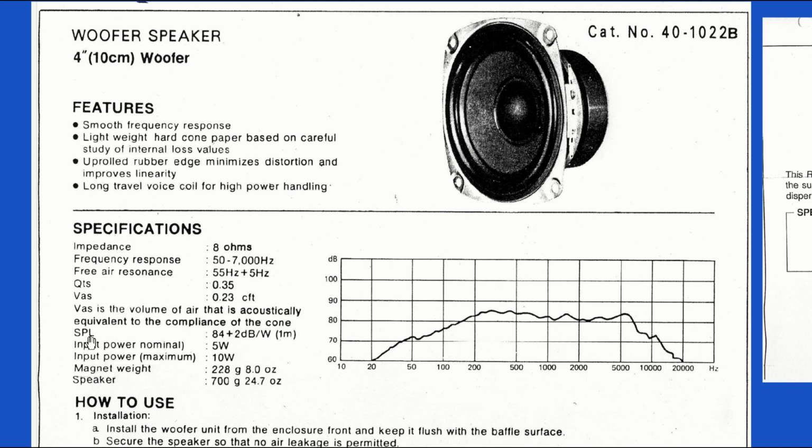At what frequency? Well, again, let's go over and look at the graph. So it looks like by the time we get to 200 hertz, we're pretty close to that 84. This is 80, this is 90, so 84 is close to the middle, so we're talking about basically a line right here. So 2 or 3 dB down from that, maybe we're at 150 hertz or something. So I'd call this 150 hertz to 7 kilohertz speaker.